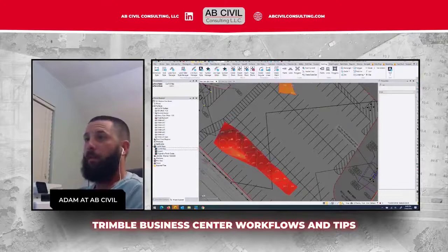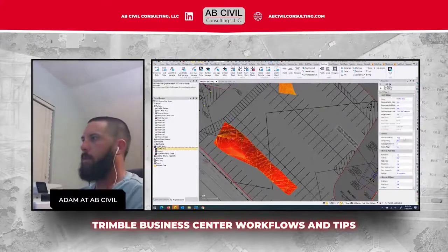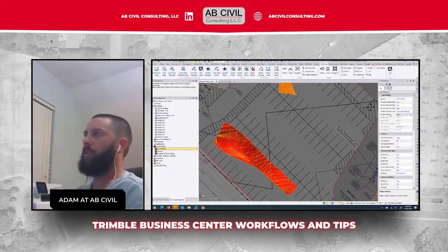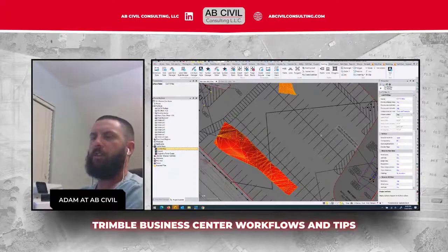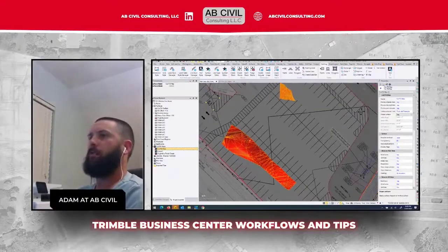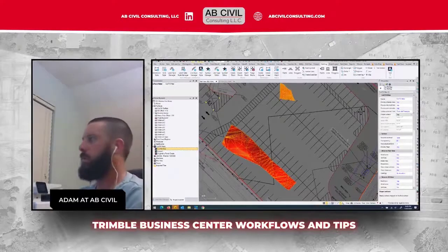Another thing with the cut fill maps, similar to what I was doing before, there's an option in here, drape surface. Display surface draped on the final surface. So this cut fill map, my initial was my finish grade. I forget now. Initial was finish grade, or my subgrade surface. Yeah. So it's going to drape it onto the cut fill map surface, or the one I made of the 3 undercuts.